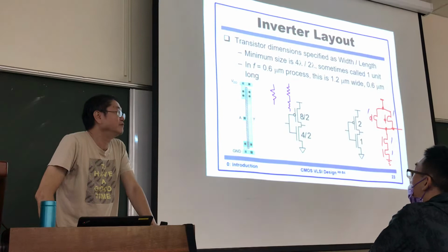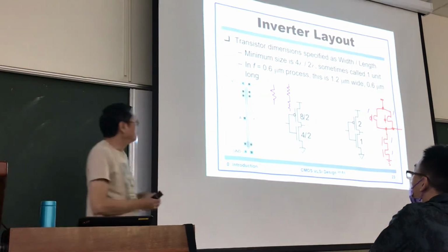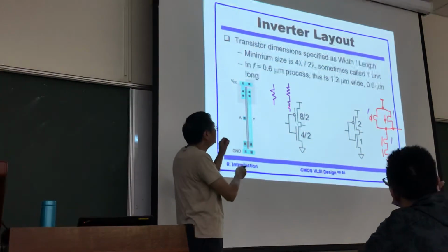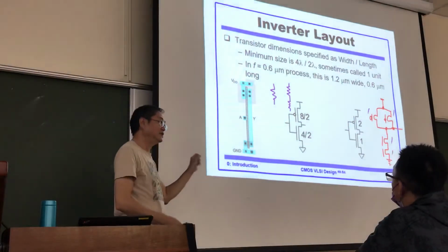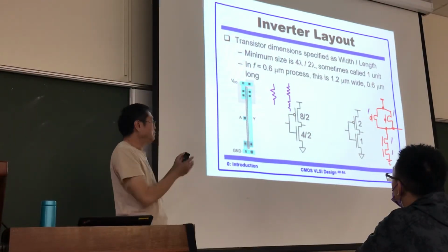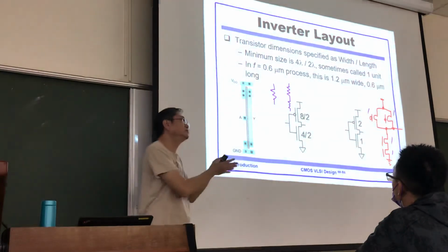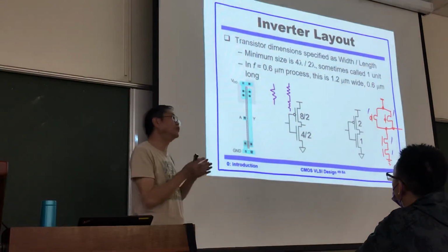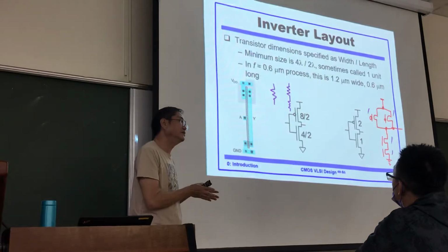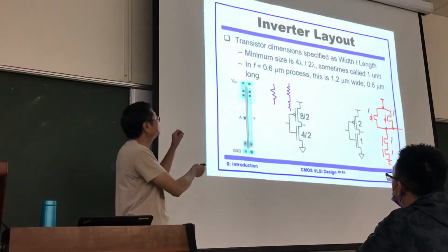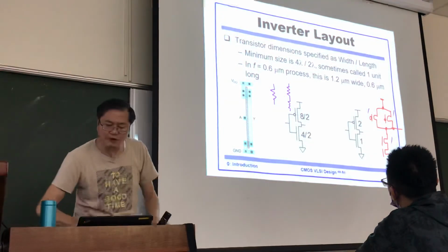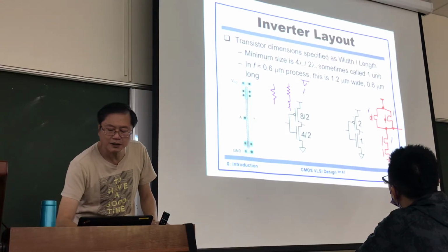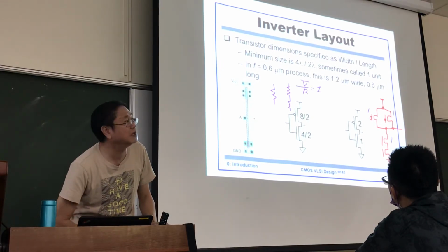Is that clear? From physics. When we connect the same resistor in series, the resistance value is double. So when the current goes through, it's getting more difficult. Given the same voltage, the current is going to be 1/2, because V over R is the current, right?